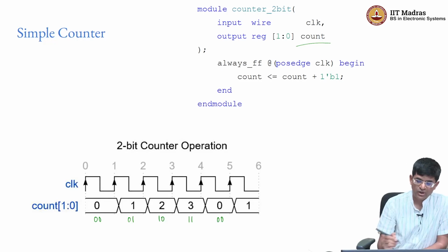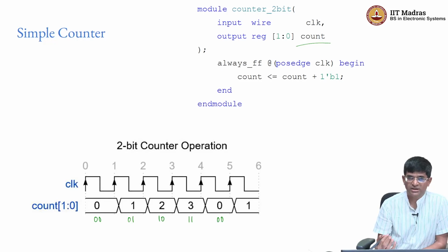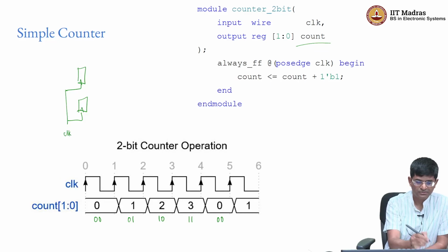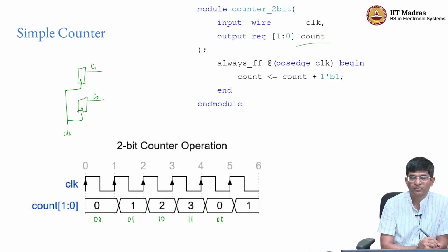Now this is interesting because it tells you that there is some logic over here, and it should be possible for us to get this right. If I think it through, it will probably require me to have 2 registers out here, both of which are connected to the same clock. The output of these essentially corresponds to the 2 bits of the output. So this would be C1 and this would be C0, right. So this C1, C0 is essentially what I am seeing down here as the different values that come out of the bit sequence, right.